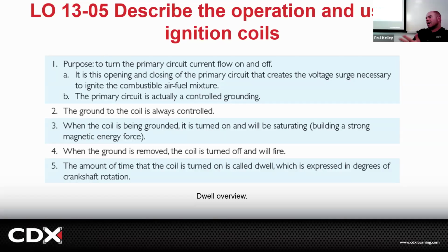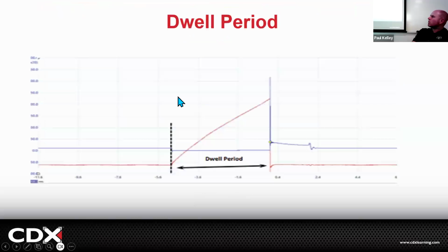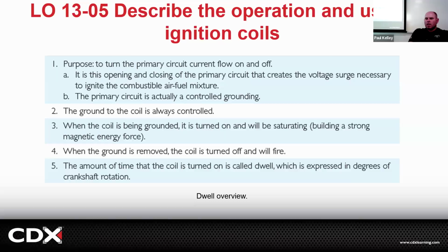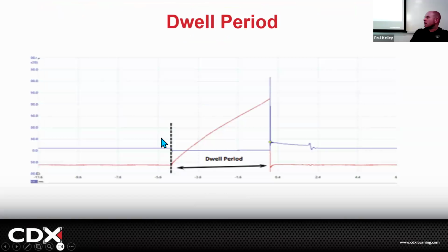Now, why don't you have spark? Again, that's kind of why we're covering all this, and we get more into the diag next time. If we had a good primary charge up, but it didn't make spark, then I might look at that spark plug, potentially, sure. And FYI, if the spark plug has a lot of resistance on it, this line will actually be a lot higher.